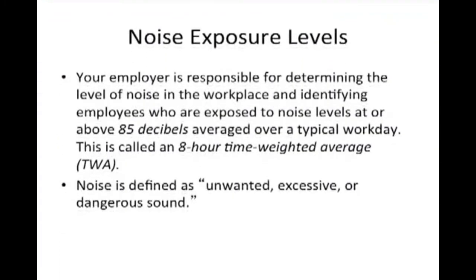Your employer is responsible for determining the level of noise in the workplace and identifying employees who are exposed to noise levels at or above 85 decibels averaged over a typical workday. This is called an 8-hour time-weighted average, or TWA. Noise is defined as unwanted, excessive, or dangerous sound.